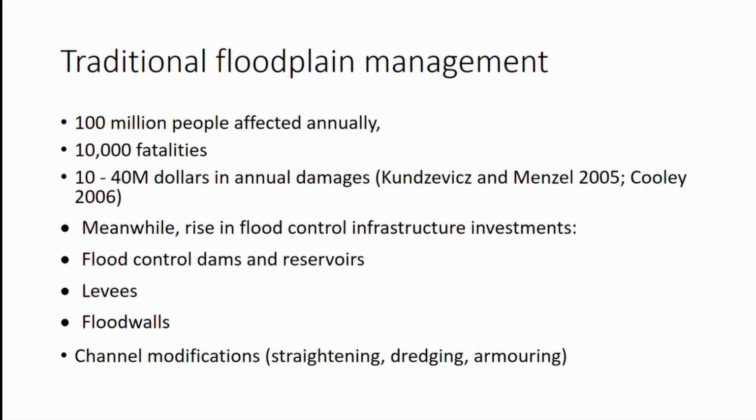You can also have levees alongside your river systems. And what the levees and the flood walls do essentially is to cut off the river flow, the high river flows, from inundating the floodplains so that lives can be saved and properties also saved. Then some approaches are also dredging, that is essentially removing sediments and organic matter from the river system and creating more carrying capacity to accommodate higher flows.